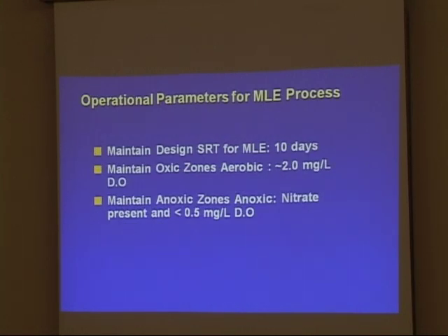Basically, for the MLE process, you want to maintain a design SRT of around 10 days. You maintain your oxic zones in an aerobic mode, basically around 2 milligrams per liter DO, and maintain your anoxic zones in an anoxic mode where you have nitrate present and, as I said, less than 0.5 milligrams per liter DO.